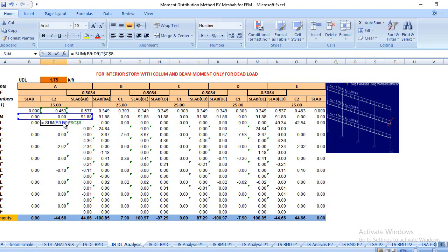Similarly balancing, you see here, no carryover, you see half coming to this side, similarly half coming to this side, but remember it is not just half, it is only this one, carryover, clear? So this moment is divided by this factor, and similarly here this moment is divided by this one, and similarly by this one. Although in our bachelor studies we basically had half the moment coming toward this side and half coming toward this side, here the carryover factor is different.